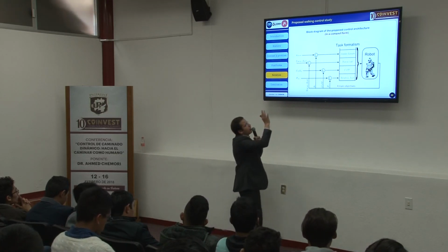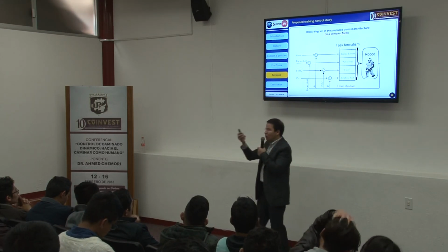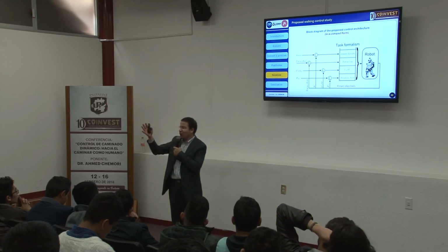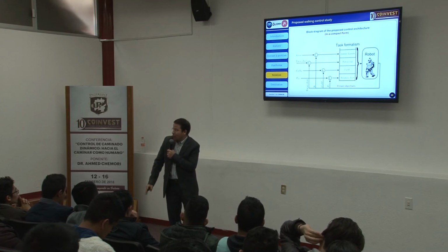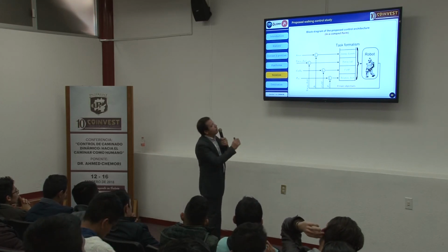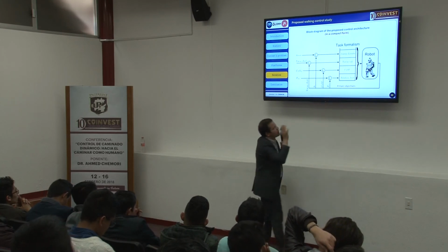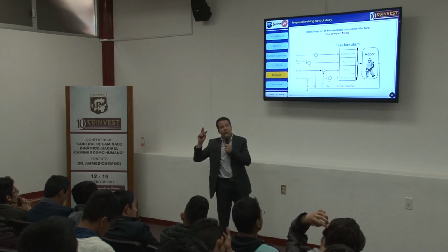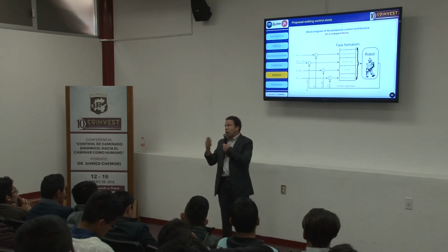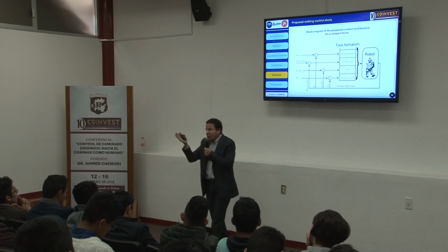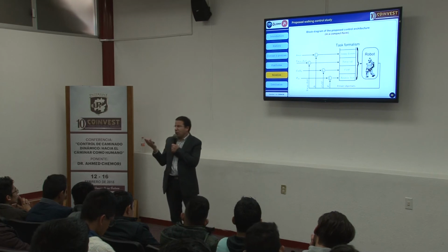But now, for sure, if we add, for instance, the joint limits, it will improve the motion, because at the beginning we didn't add the joint limits, so we obtained a motion like that. It was not good. So we added the limits to limit the motions, and we improved. Then we added the relative distance between the feet and the center of mass as primary tasks. We also added the motion of the torso as a task, such that it improves, and like that we obtain a good motion.